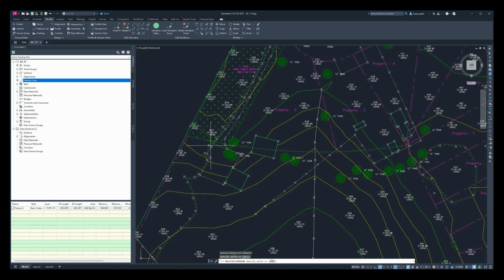Now, in most cases, you're going to have individual instances where you need to tweak or adjust and remove erroneous points individually. If you've generated elevation points while working on your drawing and design, and you've put all these out there and it's all wrong, the line's in the right location, but everything about it's a mistake, that's when you're going to use that all command to clean slate and start again, and do it right the second time.